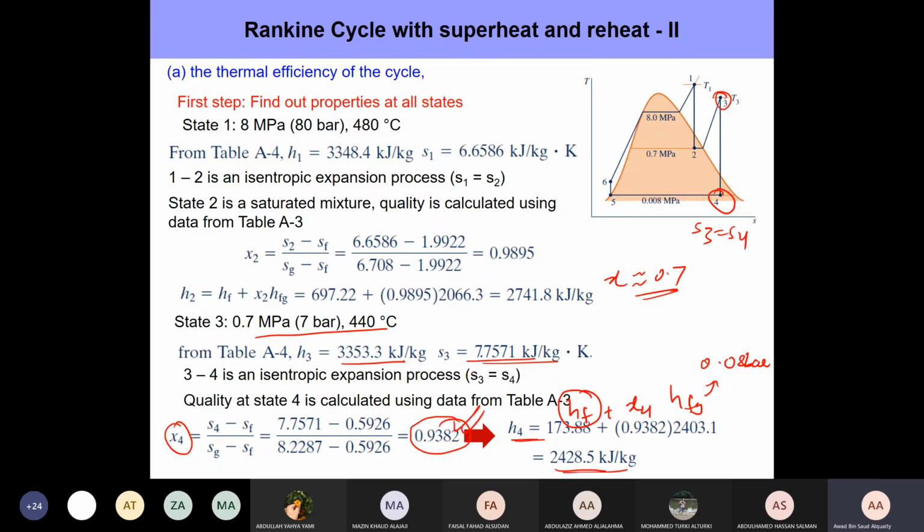And the excellent thing about this is the fact that we did this at no cost, right? We are able to achieve higher efficiencies as well as higher qualities. So this is a win-win situation, except the fact that you have to certainly put in some investment to purchase one more turbine and do some piping to send it to the reheater, which makes economic sense and pays off.